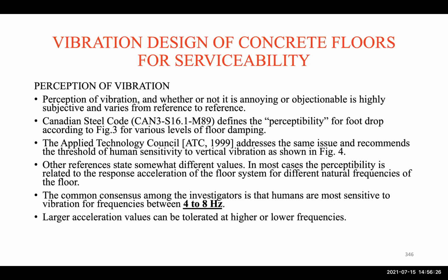Now the perception of vibration. We have different criteria for perception of vibration. Here we're talking about the human perception criteria for floors. There's a criterion provided by the Canadian Steel Code, and then there's another criterion by the Applied Technology Council, ATC 1999, and they address the same issue.